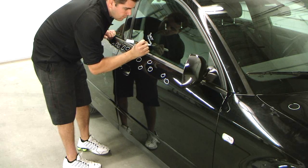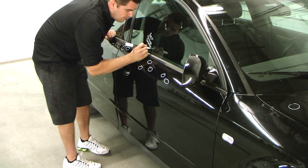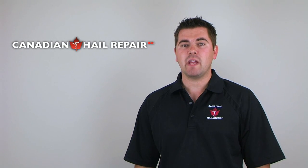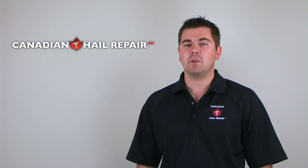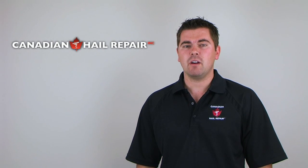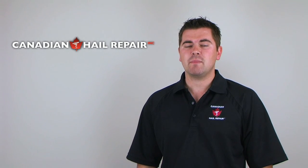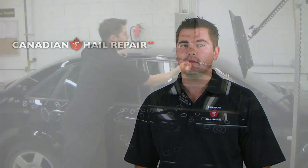When it comes to the difficulty of a repair, there are a few issues that could come up. The first issue is aluminum. Due to the fact that the aluminum does not have the molecular memory that sheet metal does, the area surrounding the dent is not trying to pull it back up to its original shape. It may take a technician up to 3 times longer and require more precision pushes on the dent versus a regular steel panel. This means repair times are significantly increased, though repairs are still possible.